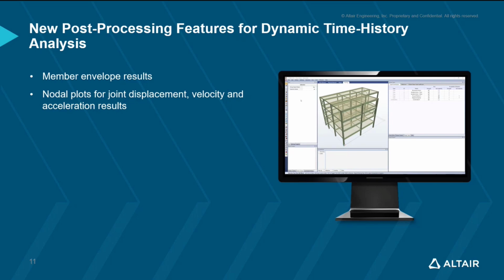So we have introduced 2 new features that help with post-processing of these results, starting with member envelope results, which gives the user a tool to understand the lower bound and upper bounds of the forces that the members undergo, as well as nodal plots for joint results, including displacement, velocity, and acceleration results.